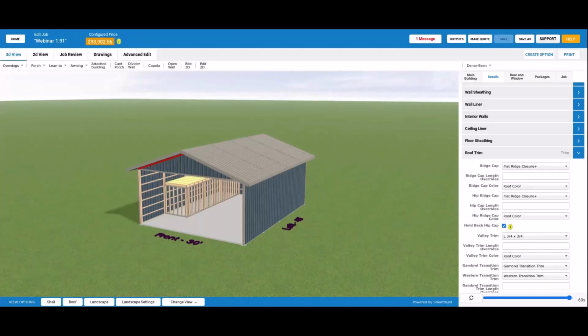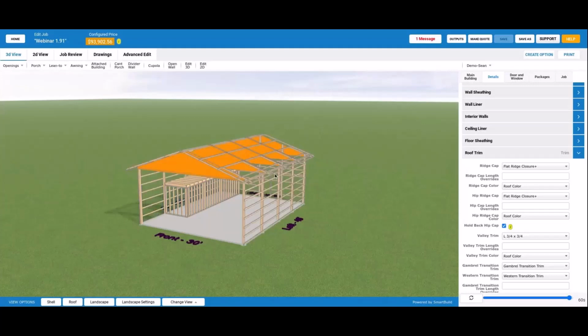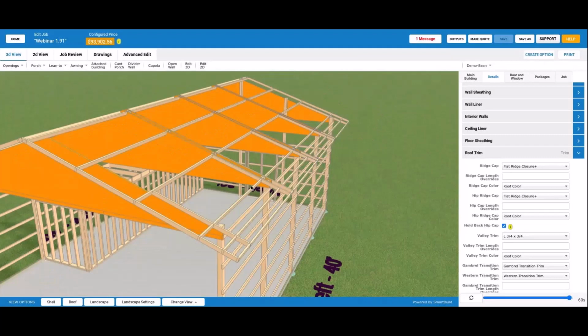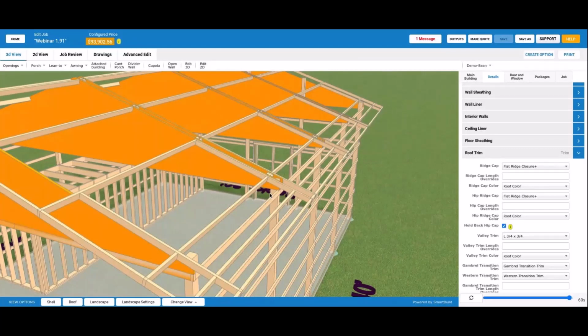Is there a setting to stagger the joints in truss carriers? Whenever you have truss carriers that are stacked, if that's what you're talking about, Chad, we just line up the joints where they line up. But I know the suggestion has been in the past that they stagger the joints for nailing, and it does throw off the lengths that they need to send out.